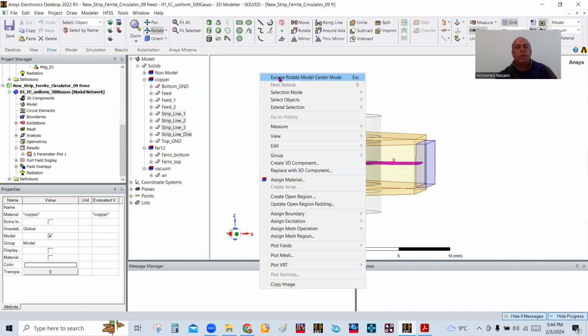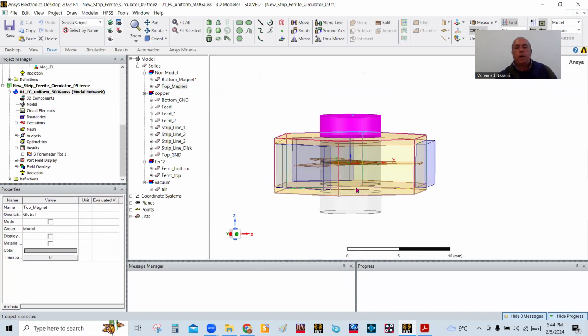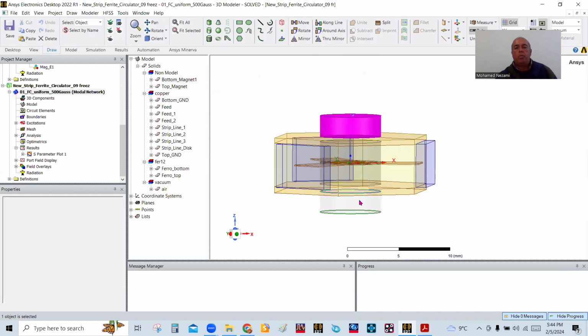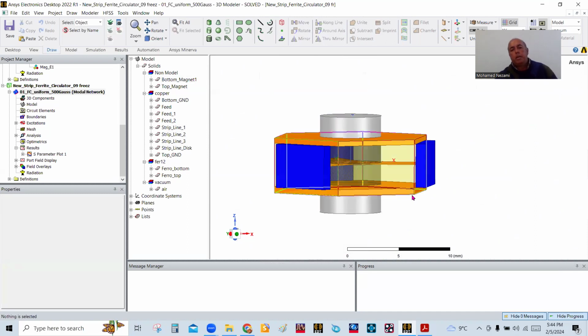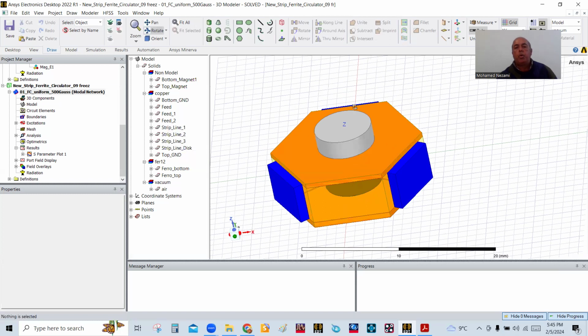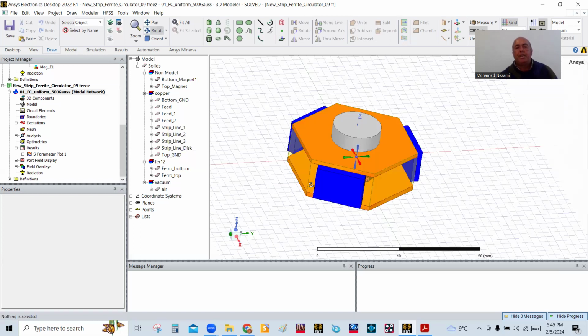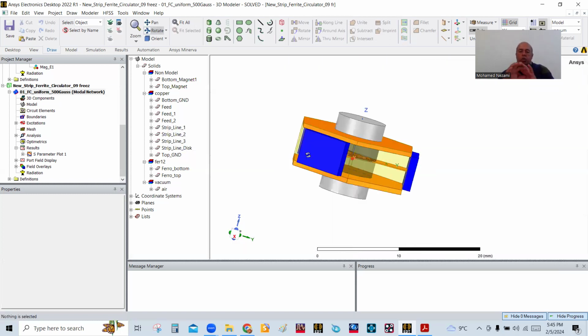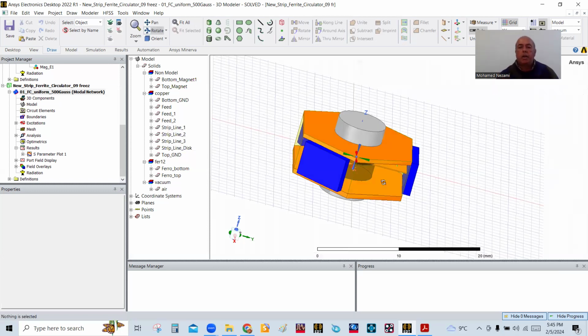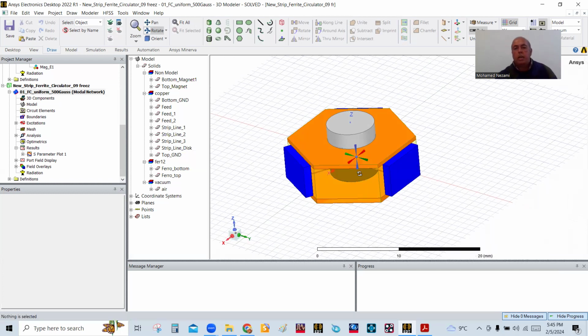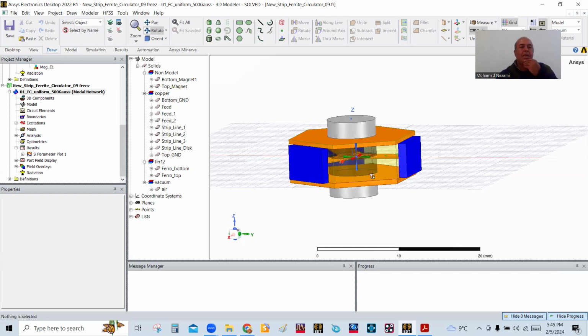Contrary to the microstrip isolator, it has two permanent magnets, one on top and one on the bottom. Okay, and it's encapsulated. The copper is encapsulated between these two. The whole thing is encapsulated. What I do here is I model this thing from an electrical point of view, but eventually this has to go to a mechanical engineer that would actually design it for real life with exact dimensions as they are in here to do the CNCing and the other parts.